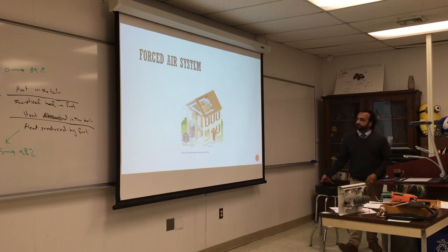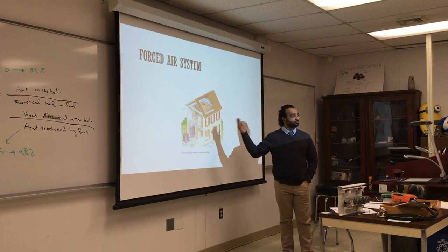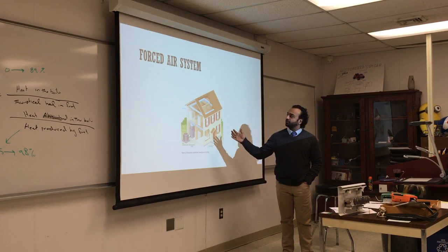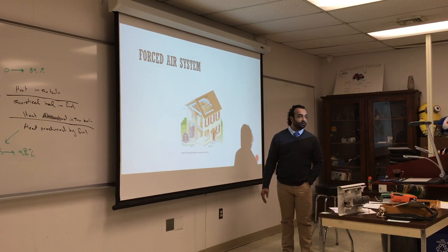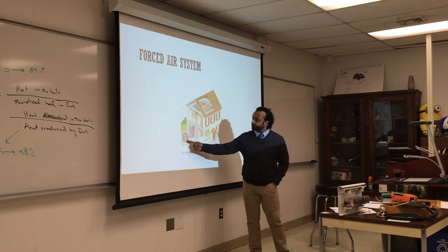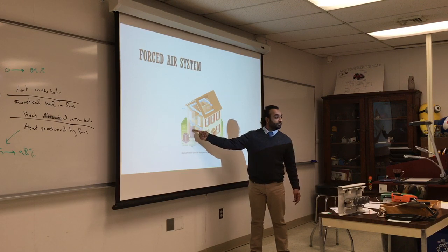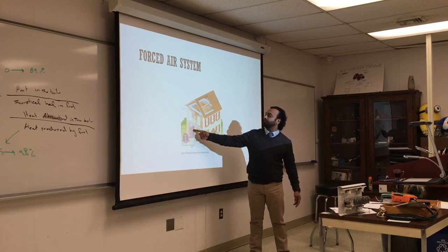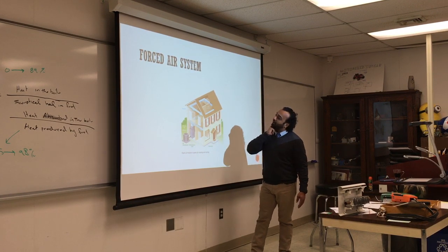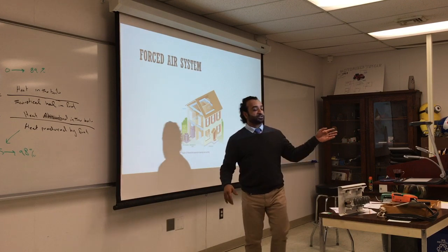Forced air system. This is for distribution. We talked about hot water distribution and radiant floor, and this is for the duct system. If you want to have central air, it's the condenser outside going through the heat exchanger here, and this can be coupled also with a furnace in the bottom. And again, you're going to have to have duct, same thing that Felipe was saying.